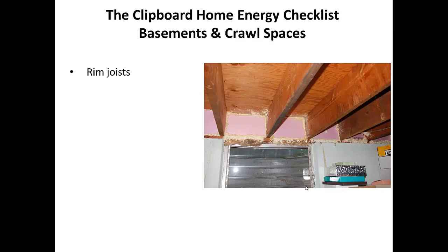So now let's go take a look at basements and crawl spaces. And here we're looking at a foundation wall and the first floor that's above it. And you can see what they've done here again with that Great Stuff foam. It looks like what they've done here is taken some blue board styrofoam and cut it fairly close to the opening dimensions, stuck it in there, and they don't have to do it a very perfect job because this foam is going to fill in any gaps that you would have.